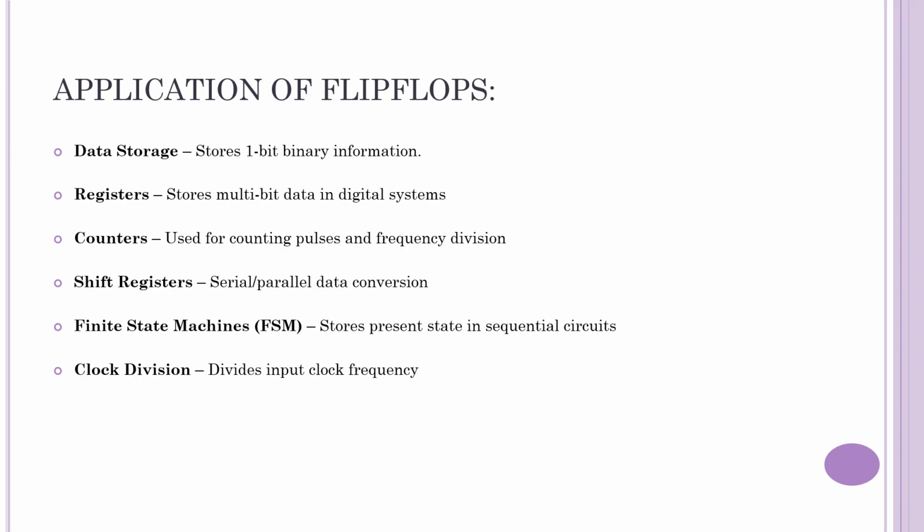Then we have debouncing circuits. Mechanical switches don't produce clean signals, so flip-flops help remove unwanted fluctuations. And finally, synchronizers. In clock domain crossing, signals can become unstable. Flip-flops are used to prevent metastability and ensure safe data transfer between clock domains.